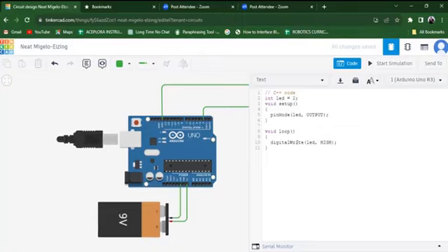Of course, I hope you can notice my semicolons at the end of every line. So always put your semicolons, right? After that, you press enter. We now tell it how long we want it to stay on. How long do we want the LED to stay on? Let's say I want the LED to stay on for 1 second. We use a function called the delay function. And I put 1000 in the brackets, right?